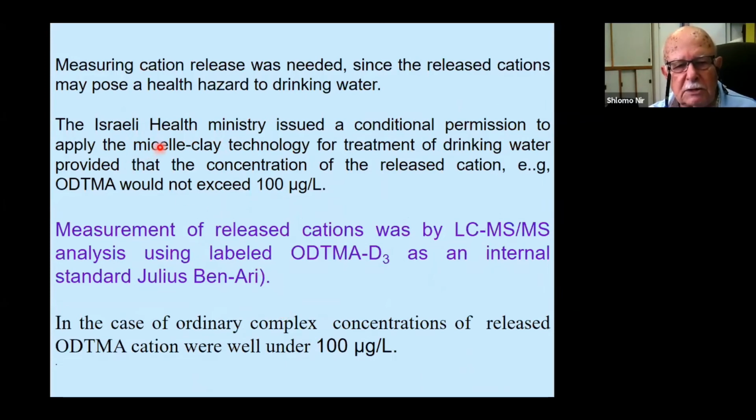In this context, the Israeli Health Ministry issued a conditional permission to apply the Micelle-clay technology for treatment of drinking water, provided that the concentration of the released cation, ODTMA, would not exceed 100 micrograms per liter. Indeed, that's what we achieved.